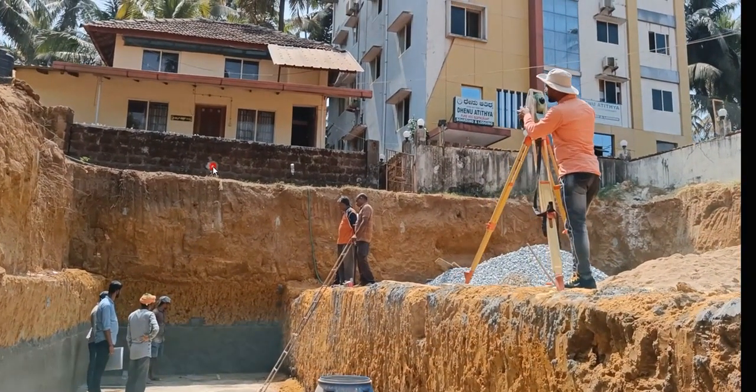Because I want the marking to be done on the ground, I cannot take the level from here. Otherwise, I should put a plumb bob from here. I should tie that line, the string, and then from here drop that plumb bob, isn't it? You're getting my point. What is a plumb bob? From here you will drop the plumb bob. So it's quite difficult. It's a bit tedious work, and the chances of error are higher this way. So instead, we told the surveyor to transfer the level here, so that it is easy for me to work on.